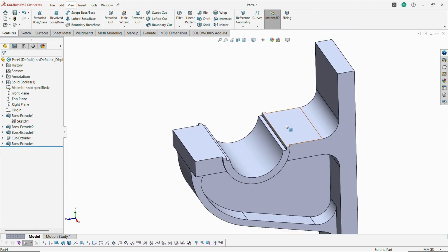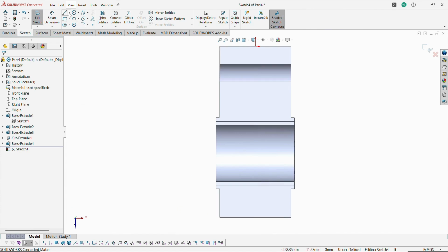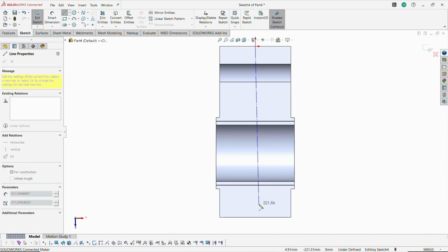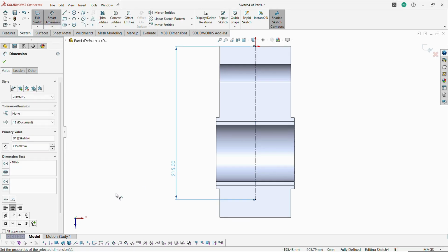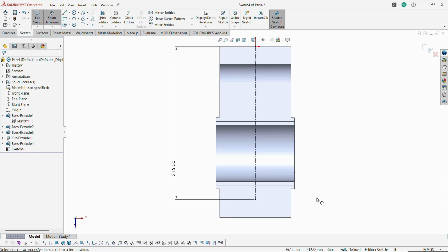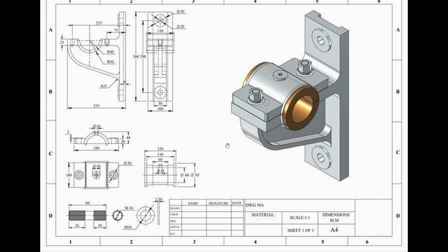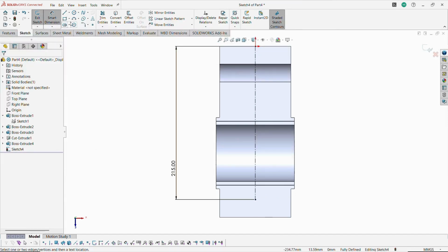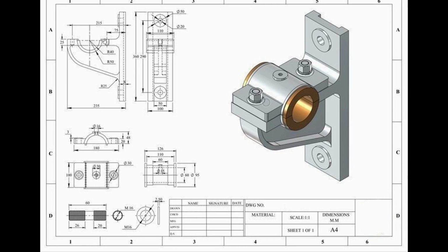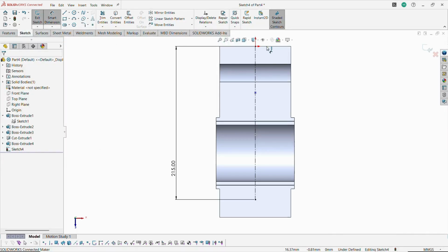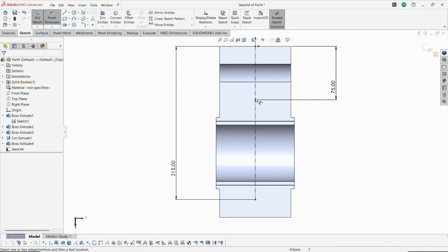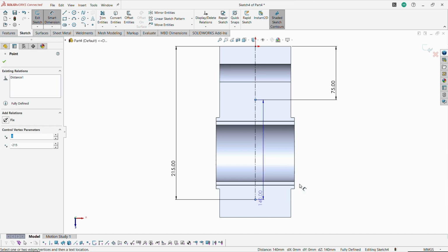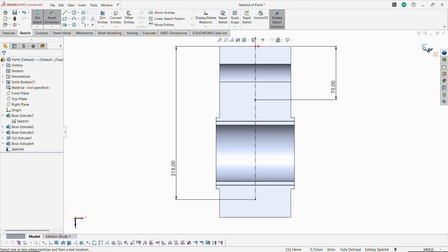this. Okay, once we created that, select this top face and create a new sketch. Afterwards, draw a vertical line profile. What is the dimension for this vertical line? It is 215 mm. Then choose the points and place them on this vertical line. The recommended point distance is 17 mm. So select a point and place it on this particular portion. Then the dimension for this vertical line is 75 mm. So mention 75 mm in this category. Almost the two different points are placed equally. One is at 215, another one is at 75. The in-between distance is 140 mm.